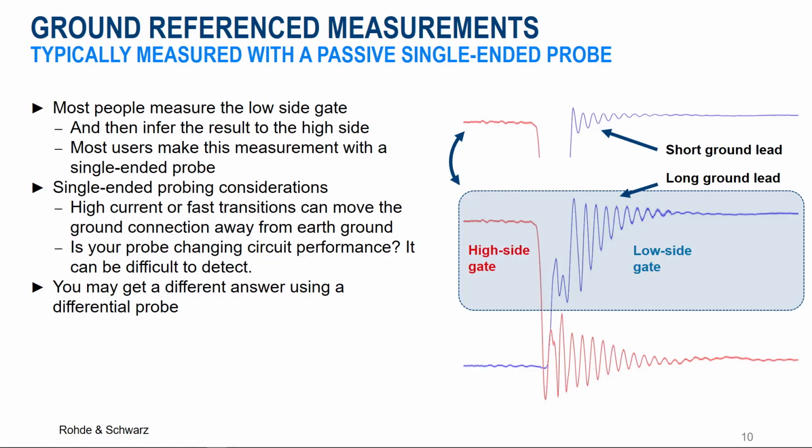Referring back to our discussion on bandwidth and proper grounding, let's evaluate the low side gate driver's rising edge using long and short grounding techniques. Comparing the different ground accessories, the question is the noise real? Inevitably, some of the noise and ringing are real. However, as you can see in these screenshots, most of this is just measurement error.